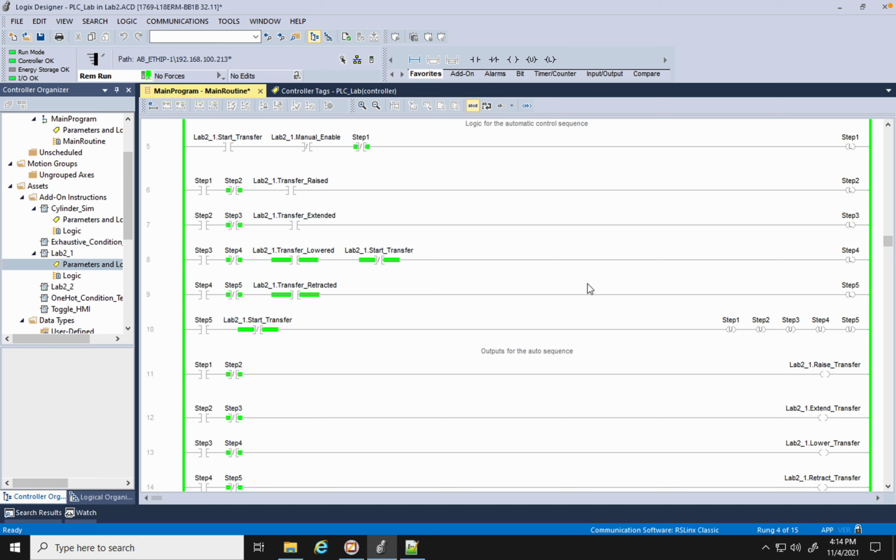So rather than saying we're only using state machines or we're only using a bit latch sequence, we used a state machine where it was appropriate, where it's driven off of user interaction. It's not a sequence. We don't know what they're going to press. We don't know what the next decision is going to be, so we don't have a way of knowing what the next mode should be. So rather, we use a state machine to be sensitive to the decisions of the user and let it be input driven rather than sequentially driven.